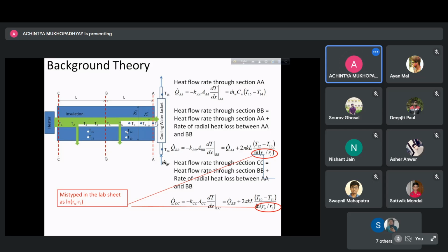Now if we assume that this entire stretch is at the same temperature, then this becomes a purely one-dimensional radial heat conduction problem. And so we know that if L is the length of the insulator, and its inner and outer radii are Ri and Ro, basically not here to here, we are interested in the locations at which the thermocouples are placed.